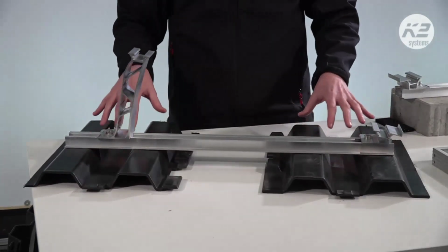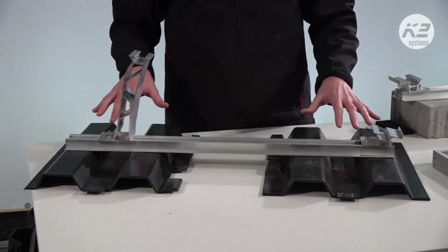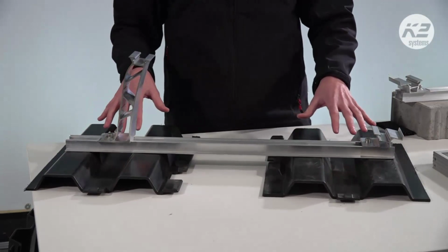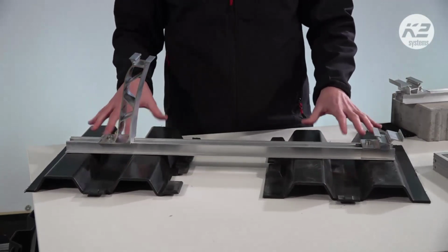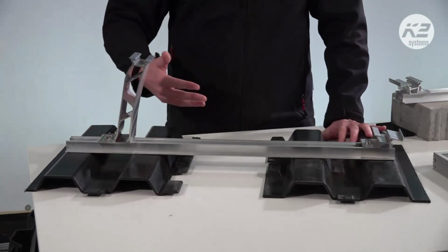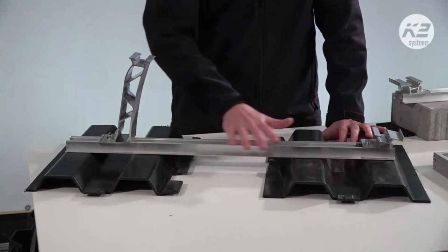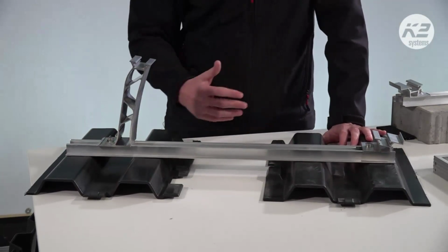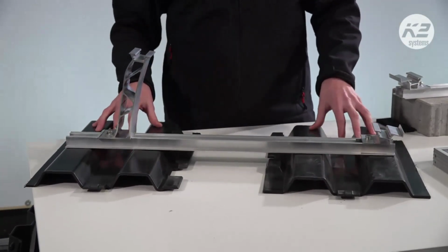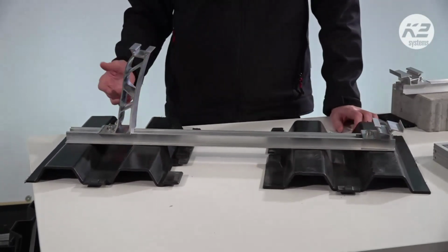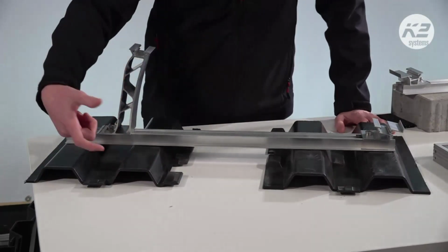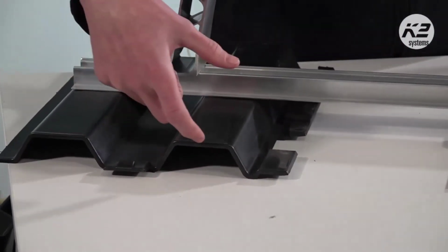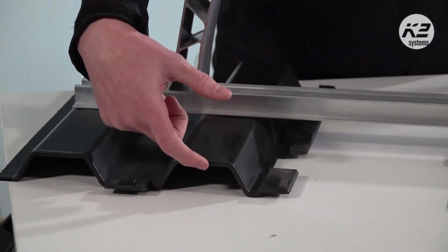Depending on the material and the density of the material, this plate now represents a certain amount of ballast, or a certain number of kilograms, which will sit on top. And this saves you then from having to put extra material on top, like actual ballast stones, what we would usually put, because this weight is being made up from the side. So we're able to also calculate this in base as well, because usually you'll have an idea already of how much material is sitting on top and a density of that material.